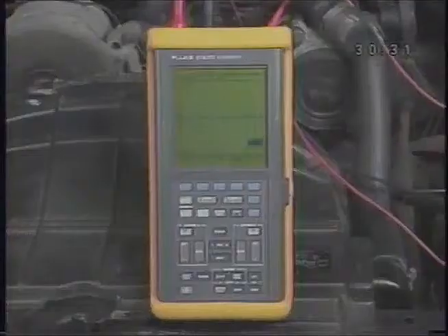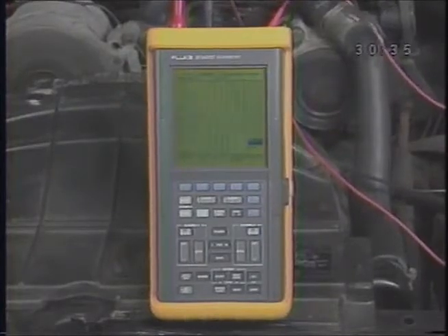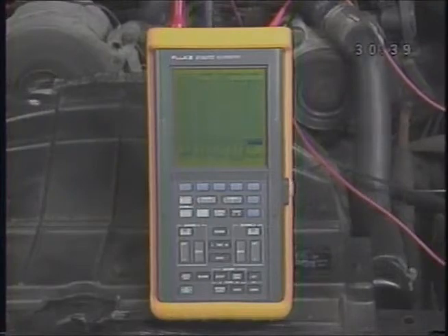Once you have the voltage scale and time base set to view this waveform on car, use these settings to replace the setup in memory number 1. So far you've been running this test with the engine cranking. One thing to remember is that there'll be a huge increase in frequency and amplitude with the engine running.